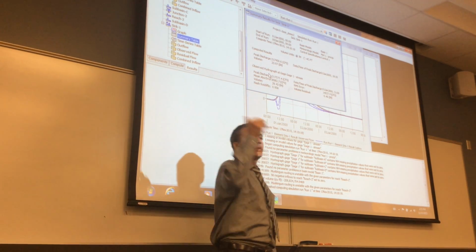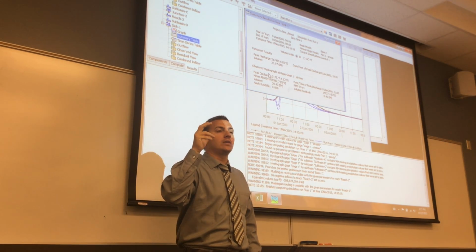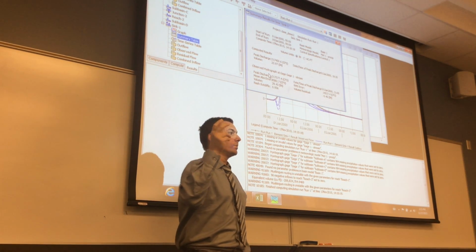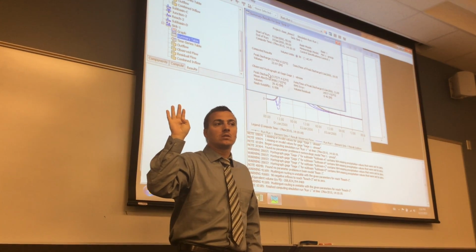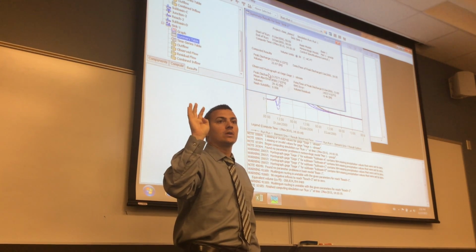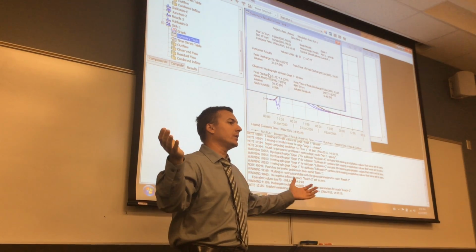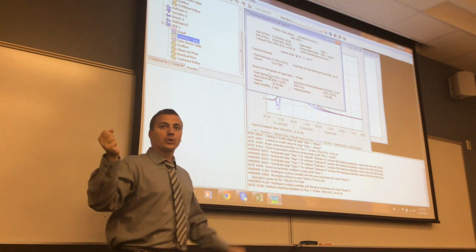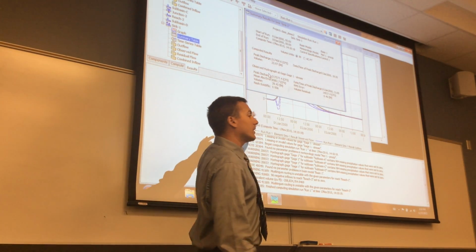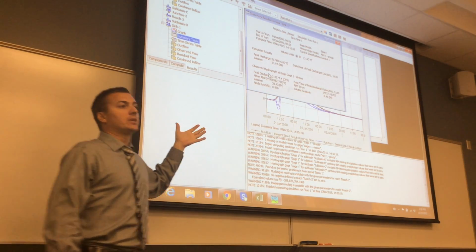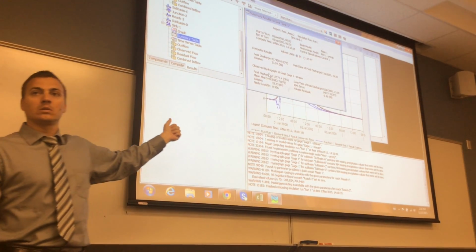So now it's time to go back to your model setup and refine your curve number. You can also refine your X and K, because those are the parameters we're choosing. Even your lag time. We only chose 4 things, so we're using a 4-parameter model here to calculate runoff, right? Those are the only things we change. I mean, you won't change your watershed area. So we could change those 4 by a little more, a little less, rerun it, and see what you get. You should be able to change those a little bit to get a better graph. Okay? Is it clear how to do that?